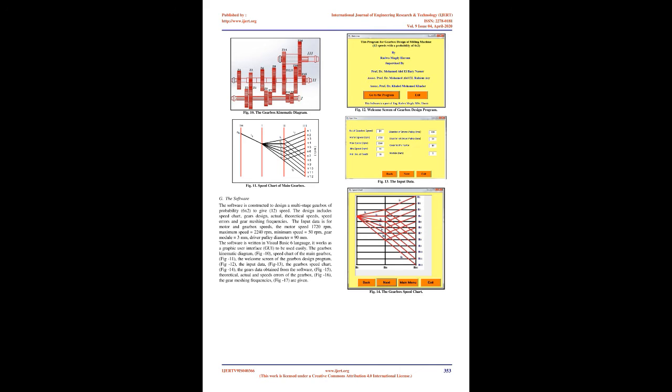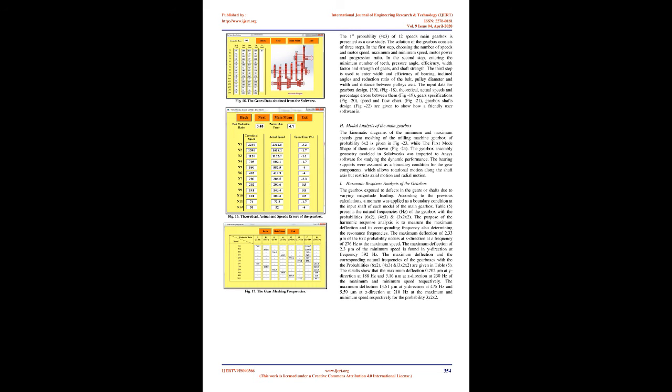Mode 1 at F equals 110.7 Hz, modification number 2. Mode 1 at F equals 109.3 Hz, modification number 3. Mode 1 at F equals 112.6 Hz, modification number 4. Original column base, free-webbed, mode 1 at F equals 73.8 Hz.